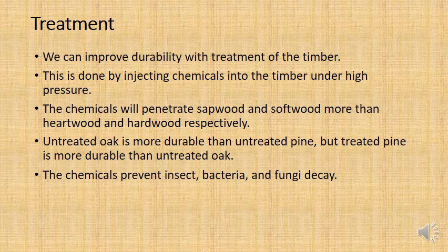Well, there's a type of treatment we can do where basically we are trying to inject the wood with high-pressured chemicals, and these chemicals will penetrate into the wood just like water would, and it's being squeezed into the wood because it's under high pressure, and that chemical will basically be poison for any insects, and so insects will not want to penetrate into the wood.